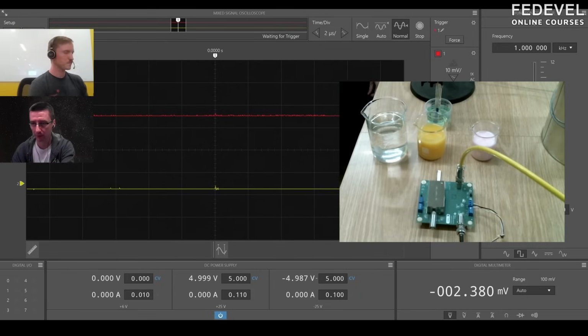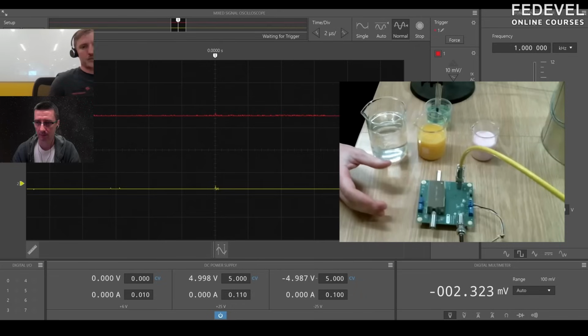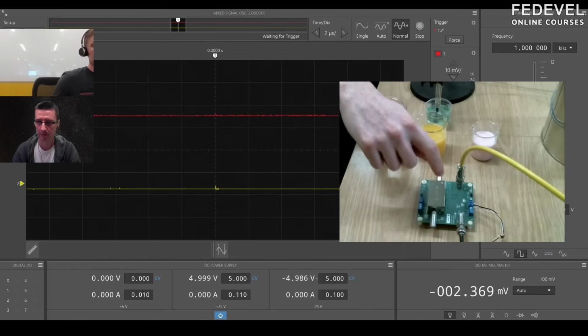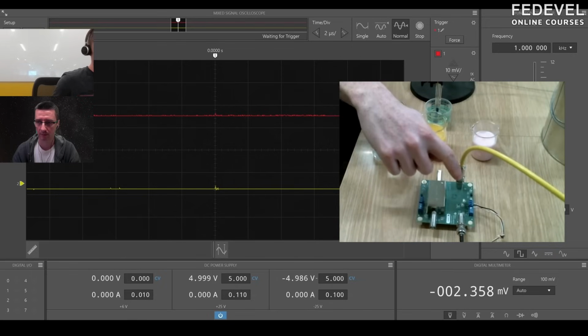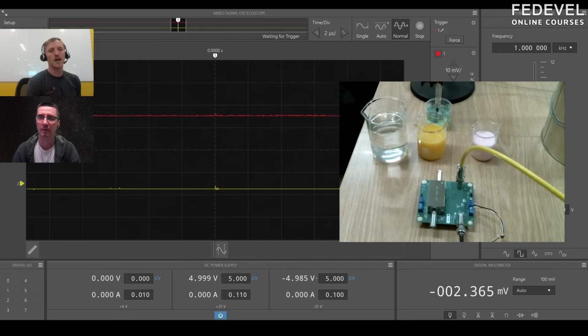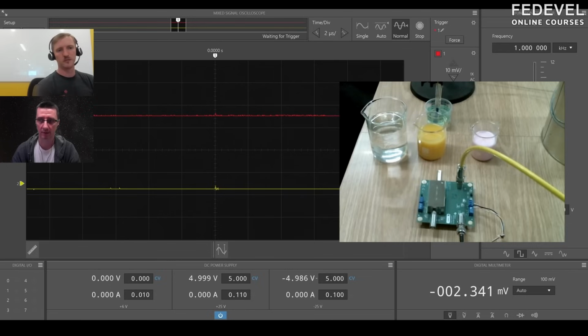And why are there 4 connectors on the board? So this evaluation module actually has 2 different circuits. We're using the one on the top here, and this is our high impedance buffer amplifier. And the one on the bottom is actually set up for a transimpedance amplifier, and that's going to be to measure very, very low femtoamp currents. This one's disconnected. We're just going to use the one at the top to amplify our high impedance signal. Okay.